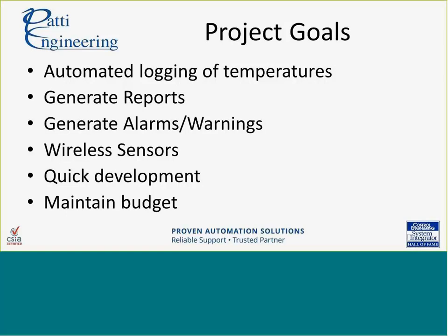Our goals for the project were to create an automated system for logging temperatures in the various zones throughout the building. We wanted to generate reports, generate alarms and warnings. They don't have an operator constantly looking at the system the way an HMI on a machine would normally be used. So email alarms were a must to let people know about impending issues. Wireless sensors was something that we were going for to avoid any downtime due to cable breaks. We also wanted to be able to quickly develop this solution as well as maintain a tight budget.